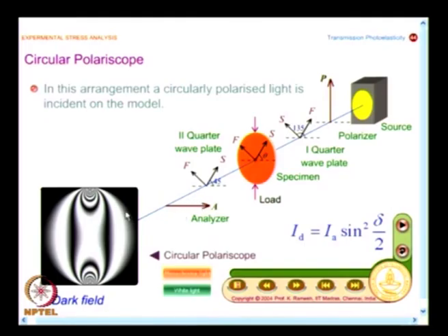So, I see fringes: 0th order fringe, fringe 1, fringe 2, fringe 3, fringe 4 and so on. So, a logical explanation is a lot simpler and straightforward in this case. It is not difficult. If you understand the meaning of a full wave plate and also understand the basics of how a retardation plate operates, you are able to conjecture I will have only one set of contours, I will not have isoclinics, I will see only isochromatics. This is what we saw.